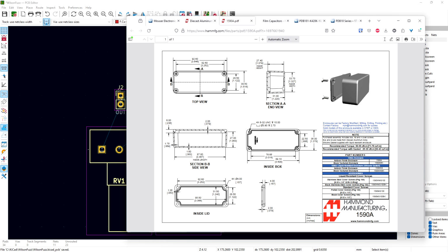So here we're saying 27 millimeters. This is going to go all the way to the lid. Problem, the lid has slight width, so that limits our inside width by maybe a couple of millimeters. So these are all things we need to be careful about. You can't just go and do random stuff. We need to be able to fit it, and we need to know on which side we're going to fit it in the enclosure.